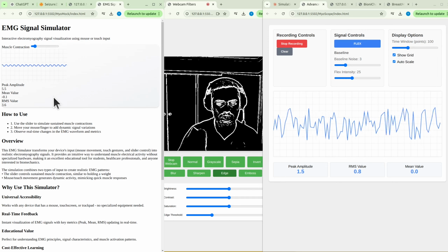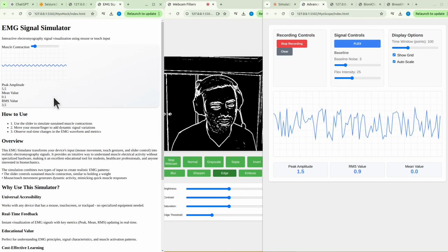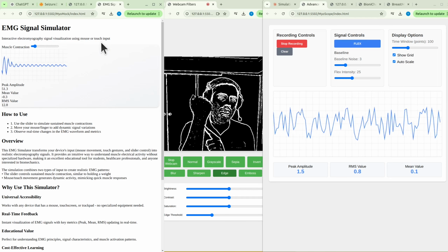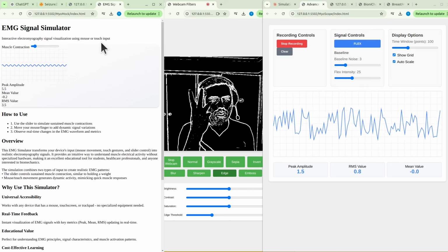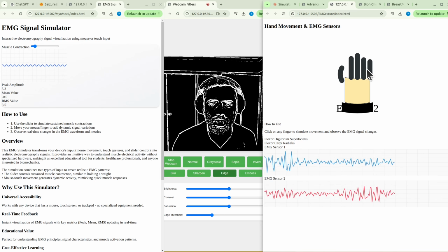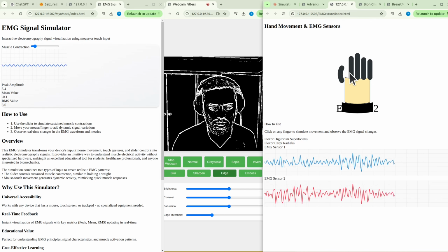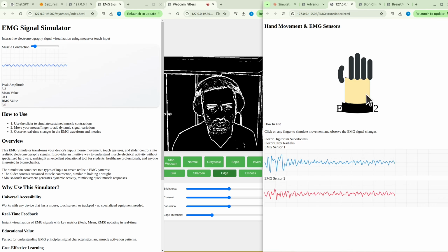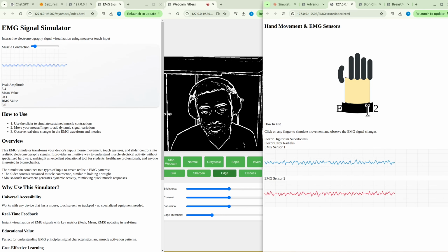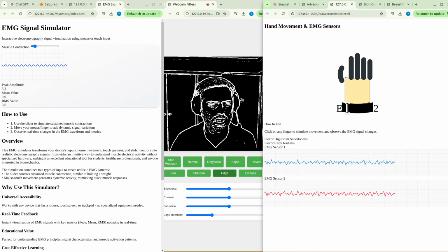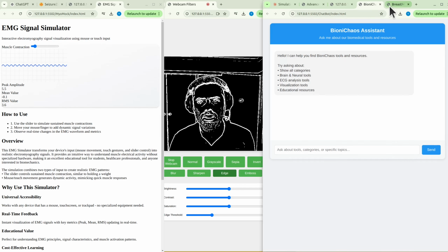Yes, so with an actual EMG on your hand, you can detect, not quite exactly, you will have an artifact crosstalk between different muscles. So even if you have your electrode over here, you should, in theory, like we're doing over here, be able to detect which finger is moving, and this is what this is a model of. So in this case you have EMG artifact on both electrodes. In this case it's stronger on the red electrode. They're meant to be a red circle and a blue circle there. I have to fix this. We'll be doing that one next.